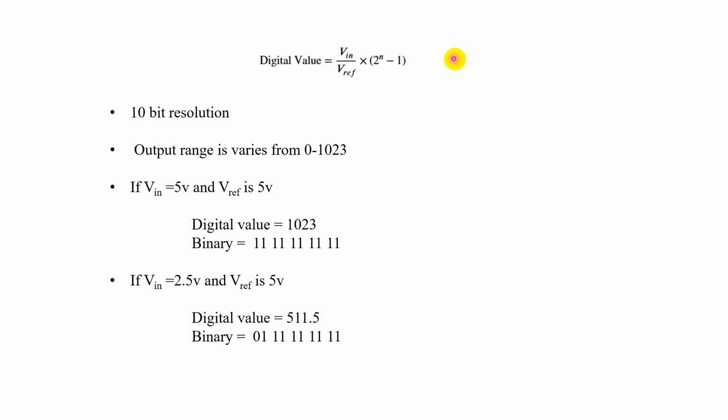That Vout is the output of this analog sensor that is fed to the input of our microcontroller, that is called Vin. The Vin is nothing but the output of the sensor which is given to the input of our microcontroller. And Vreference is the maximum measured voltage of this sensor, that is called Vref, almost 5 volts. Whatever we give as plus VCC for our sensor, we will assign as the V reference.